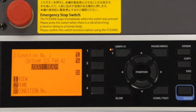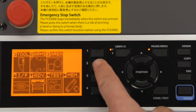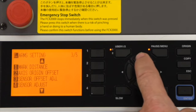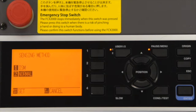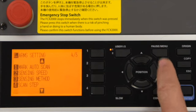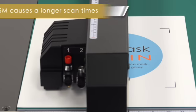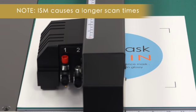To enable ISM, press the pause menu key. Press the 2 key for arms. Press the up arrow key twice to page 4 of 5. Press the 3 key for sensing method. Press 1 for ISM. Press enter to set the value, and then press the pause menu key to set the cutter to ready status. Again, this function is only necessary for media where the sensor has trouble detecting marks.